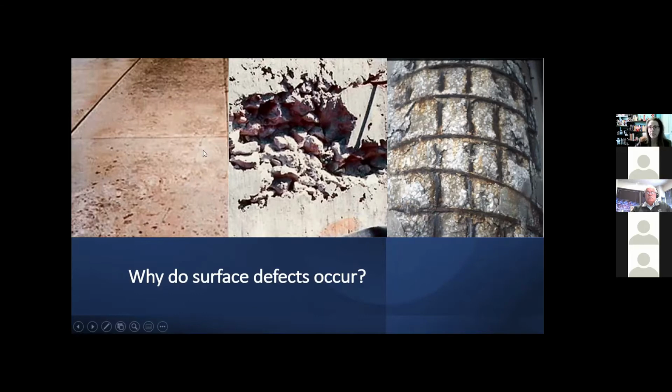So when I look at this scale, the spec itself might not have had a high enough bar in the minimum design requirements to be able to handle freeze thaw. When I see the consolidation issue, I wonder if you qualified the mixture by a maximum slump, thinking that that determines its quality and therefore had really just made placement issues for the contractor. And when I look at the corrosion, I want to know what type of maintenance was on this structure, what type of serviceability plan they had, and what type of repair plan was part of that specification as well.